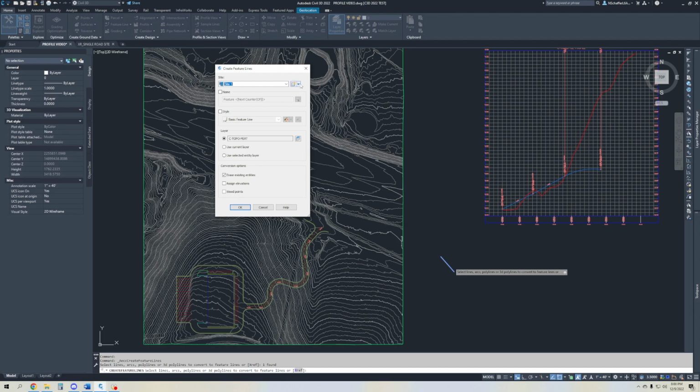You can create your own, or in this case, if you've already created a bunch of them and you already have line work and feature lines that are on these sites, you can click this drop down and select it from your drawing. If you know that this one specific parcel you want to add more feature lines to, or more grading objects, or another alignment, or anything, you can select that specific parcel. So that'll put that feature line on that site.